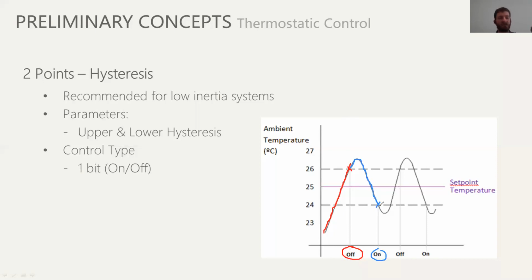So because it's, again, low inertia, I'm turning on the system again. It's on, and in not a very long time, it will start to heat the room up again. And it will be heating all the way until here. And then again, so that's the principle of 2 point hysteresis.